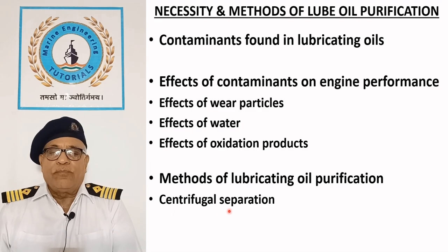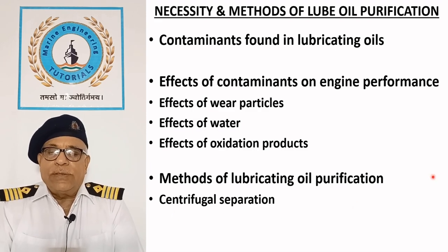Centrifugal separation. It uses centrifugal force to separate wear particles, sediments, and water from lubricating oil. It is operated continuously as a bypass to the system for maintaining the oil quality.